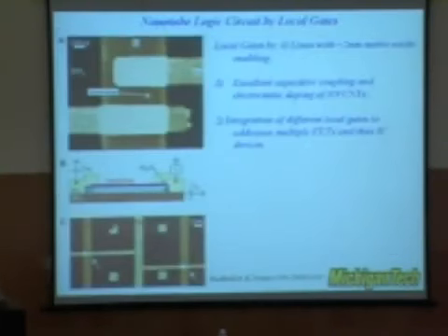And actually, a few months later, a paper in Science progressed much further from the idea that I showed you just now. In this case, it is using a local gate. The so-called local gate means each conduction channel has its own gate electrode. You can see here that you have an aluminum line, and each of these aluminum lines will have a very thin layer, about 2 nanometers thick, of the native oxide. They will enable the switching of the gate of your transistor. And you will have a piece of carbon nanotube lying across these 2 electrodes, which are source and drain here.